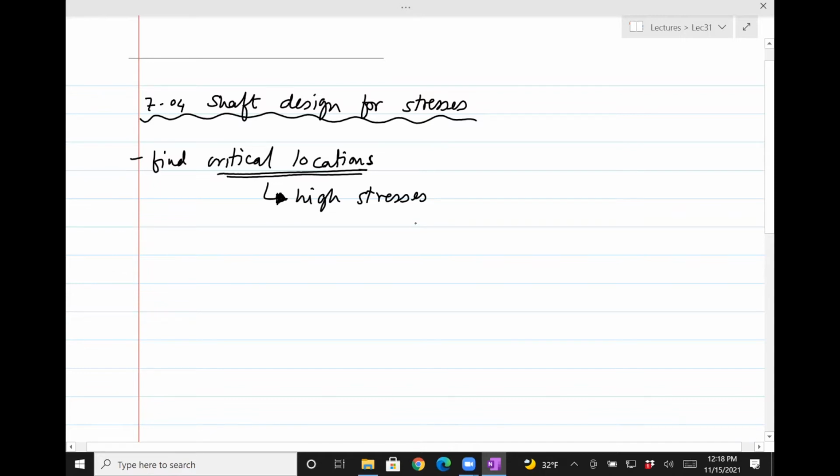So we're talking about a shaft that has some loads, right? And then you want to figure out, first of all, where along the length the stress is maximum, and for a particular section, whether it is at the outer surface or in the middle. So it's just a matter of what we've been doing before, which is the bending moment and shear force diagram, and using that. I don't see how integration can be used.